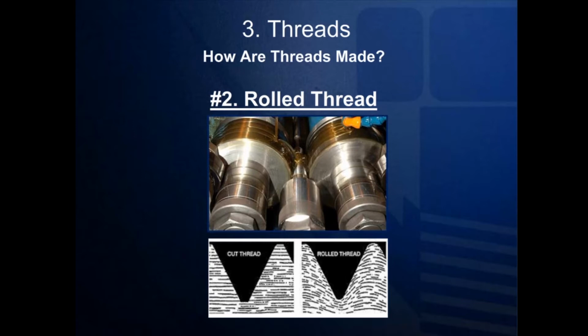Another advantage is that because a roll threaded bolt has a smaller body diameter, it actually weighs less than a full bodied counterpart. This weight reduction reduces the cost of the steel, galvanizing, heat treating, plating, and freight, and any other costs associated with the fastener that are based on weight. Another advantage is that cold working makes threads more resistant to damage during handling. Rolled threads are often smoother than those made via cut thread.